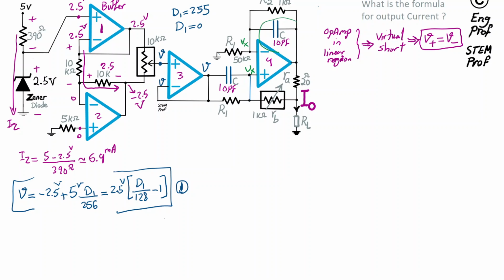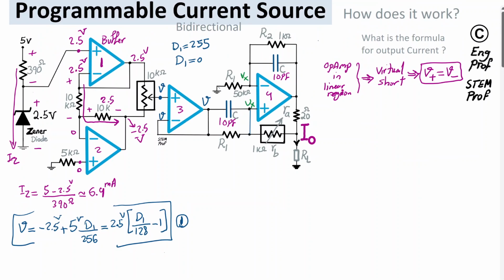Those are for only stabilizing and making sure that the negative feedback is dominant in the circuit, just stabilizing the last op-amp because it has both positive and negative feedback. Now, it's actually just the voltage division between R1 and R2 to get to the output of this op-amp. So V4 is simply a voltage division, V4 and Vx, just basically voltage division between R2 and R1.